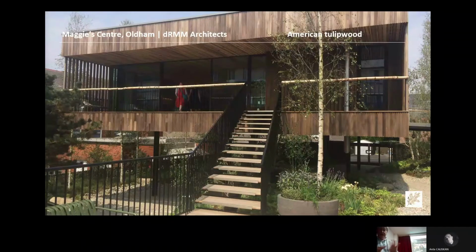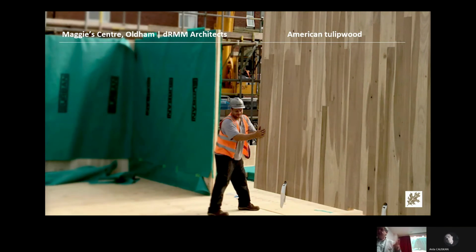building. Outside it's all clad in tulip wood, but it's thermally modified tulip wood. I won't go into that in detail now, but it enables tulip wood, which is not durable, if you modify it, to be able to use outside for cladding and facades. But the interior and the structure, the structural fabric of the building is all in Tulip Wood CLT. So it's the first commercial building using structural CLT in hardwood, which is Tulip Wood.